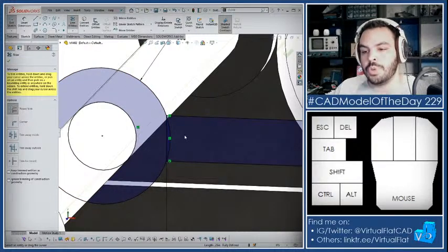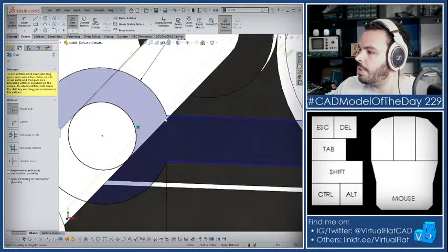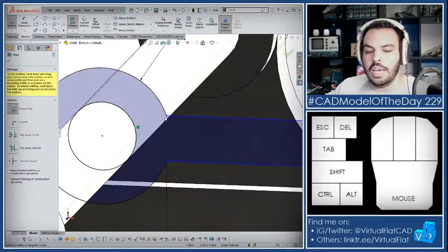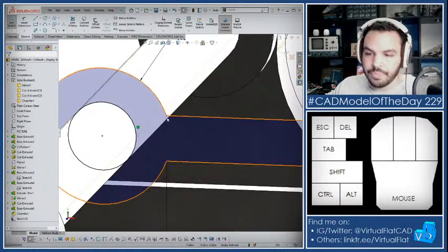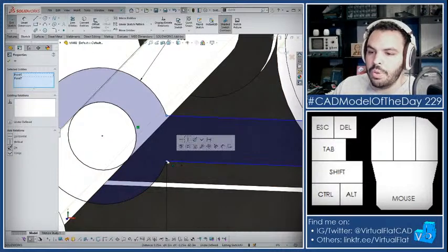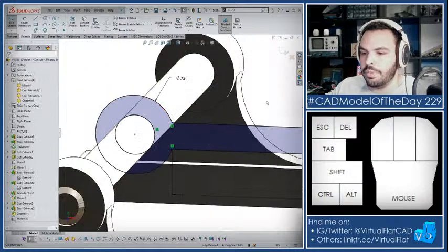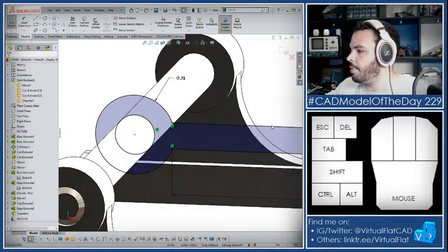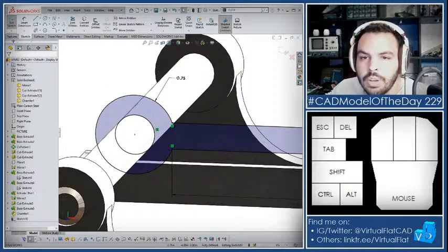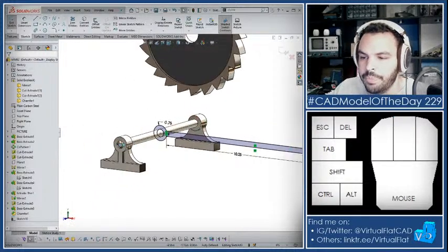So if I grab my trim tool and destroy it, there's nothing telling these points that they should be on top of each other anymore, and thus you have underdefined geometry. One way to fix it is to grab those 2 points and tell them yourself, be vertical. And you're fully defined again. I get a lot of people that stumble onto that as well.